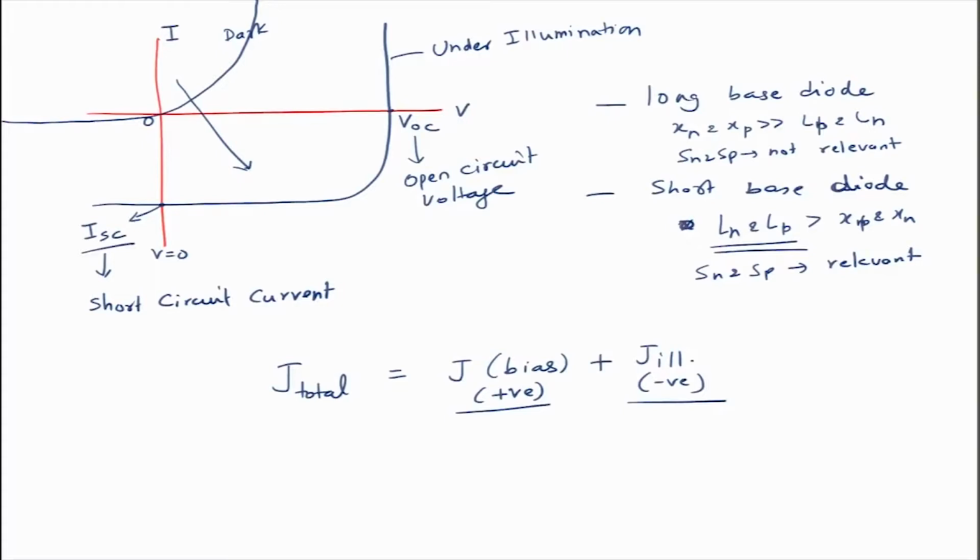And we also looked at the effect of various parameters on the quantum efficiency. Quantum efficiency shows a behavior like this. A perfect quantum efficiency would be something like that. So, this is quantum efficiency as a function of wavelength. Whenever the quantum efficiency reduces on the lower wavelength side, it means the top of the solar cell is playing an important role, so this would be the top part contribution,